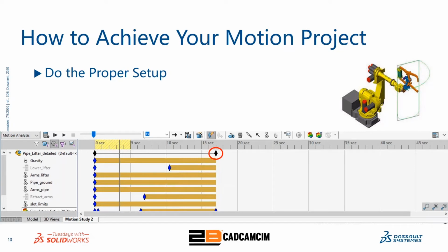The blue key is for each parameter in the motion analysis. So the components, the connections, the motors, everything in the motion analysis is represented in the timeline with a blue key. When you try to control that parameter, you only have to control that blue key.